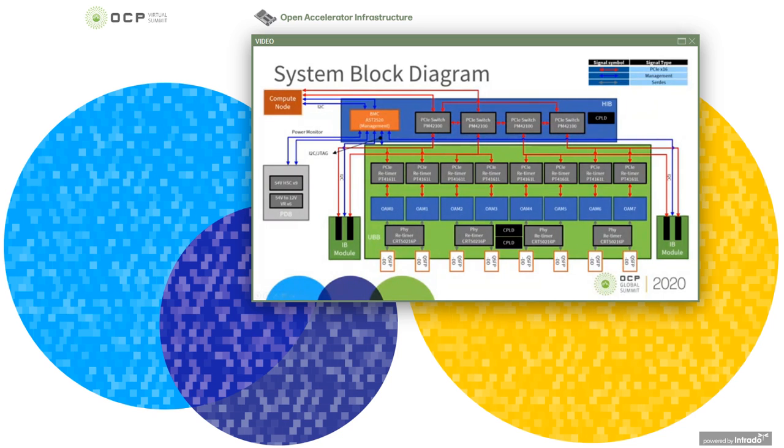So each switch connects to 1 pair of PCIe x16 to OAM, 1 pair PCIe x16 to the host, 1 pair PCIe x16 to the PCIe expansion slot, and 2 pairs PCIe x16 to the other 2 switches. There are a total of 96 lanes here, and we reserve 4 lanes for management.